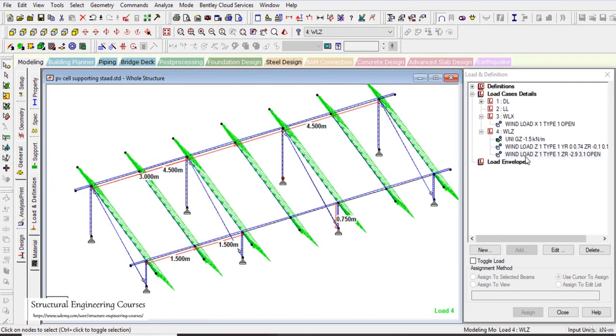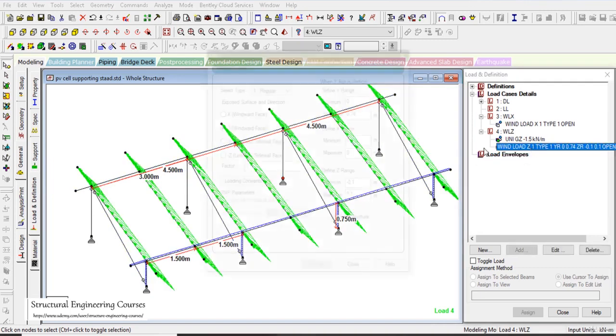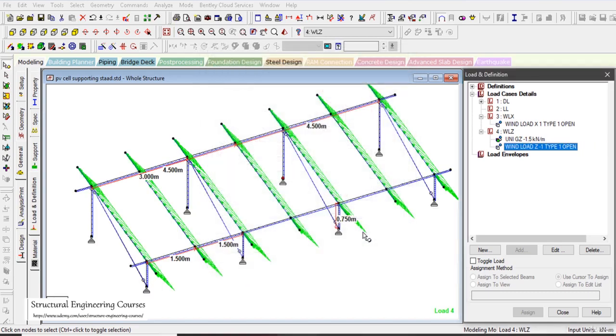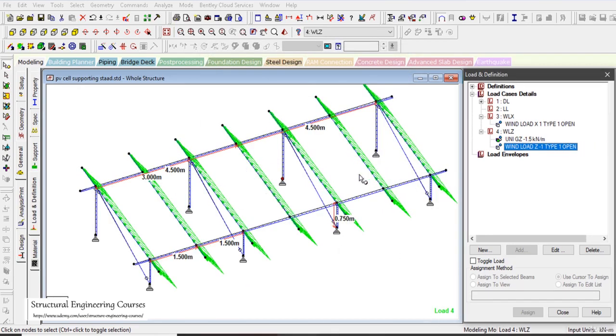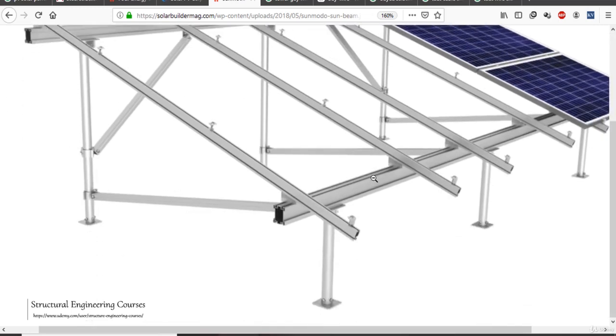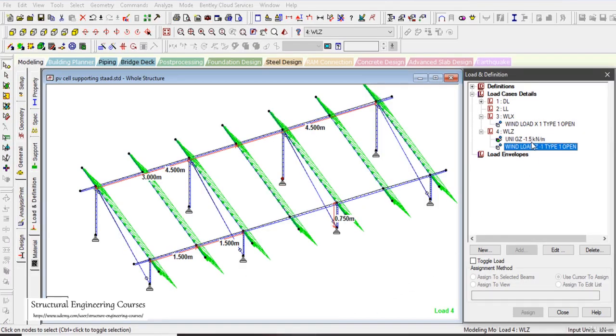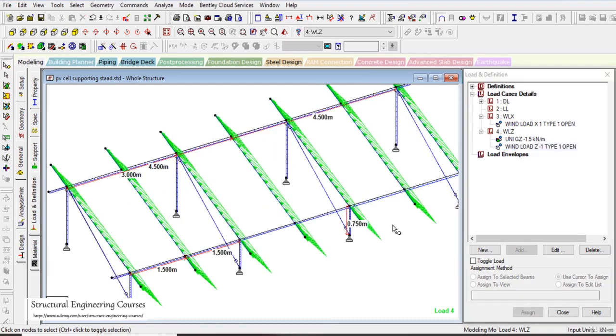Or what we can do on the conservative side is that we can just delete this range. So that wind load shall be applied on all the members here, because there's also another concept that maybe wind can go like this, and then it may act on these members here. So to consider surface area for wind which may go down and act on all these members, I shall propose that we can apply with this approach also.